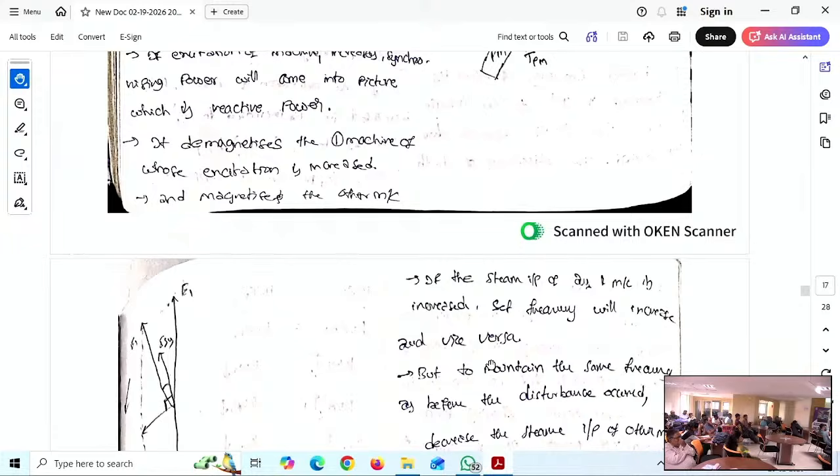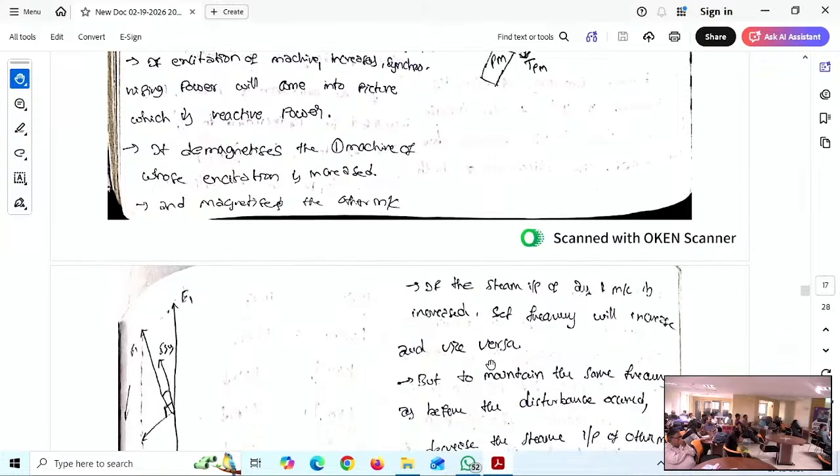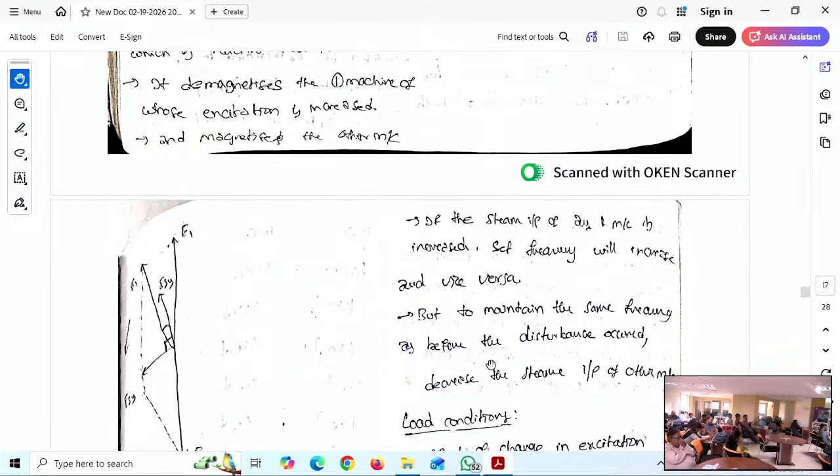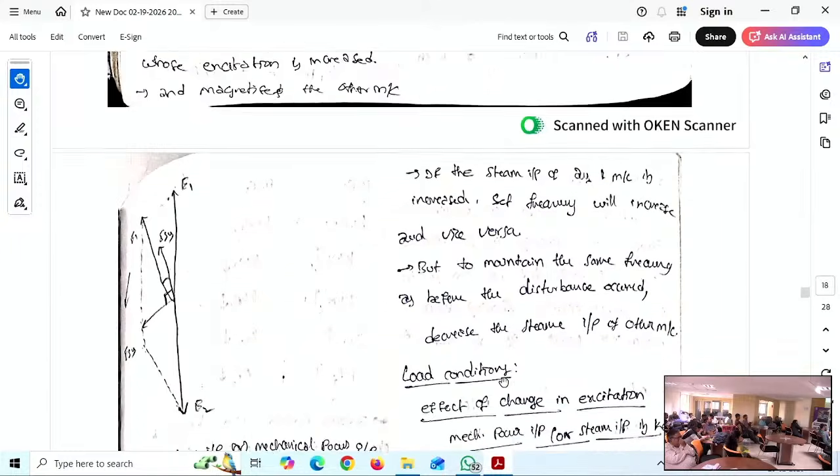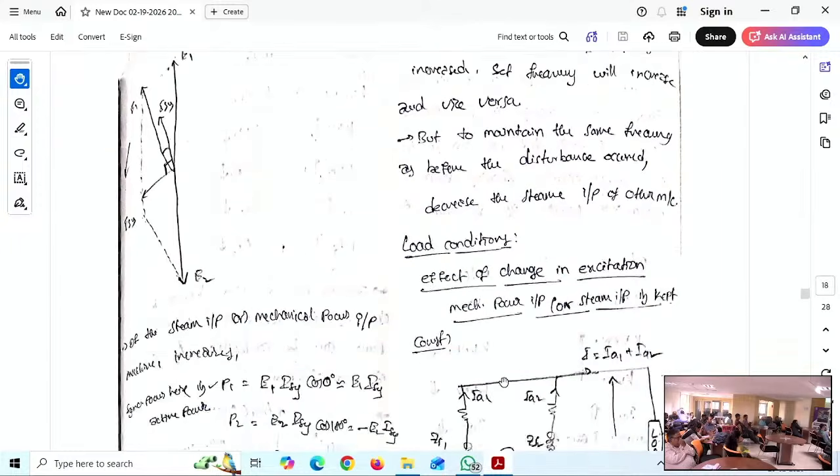The set voltage on the panel we are seeing is greater than the rated. Something happened at the control panel, so we reduce the excitation. Then we do the control and operation management at the station. This is one of the aspects I used to tell students: we used to reduce the excitation.